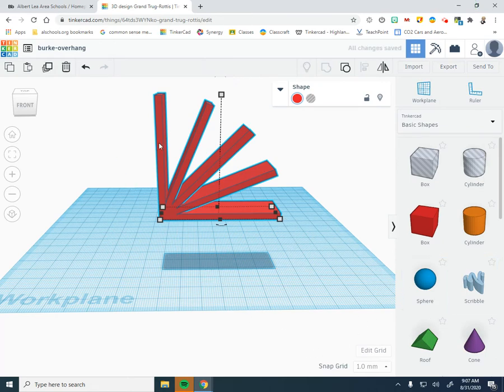We've got our 0-degree angle. This is going to print perfectly. 22.5 degrees will print nicely. 45, this is really our limit. And you'll see this when we print your model. When we get to the 67.5, you're going to start to see some problems printing. The 90, absolutely going to see some problems. But here's what's happening: the 90, we've got to elevate it off to show where it is.